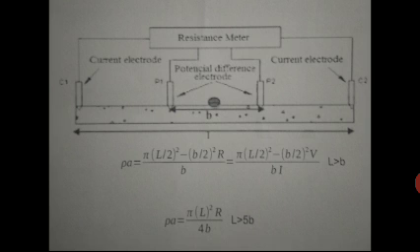In this method, four types of master curves are interpreted depending upon the resistivity variation with depth, that is A, Q, H and K type curves.